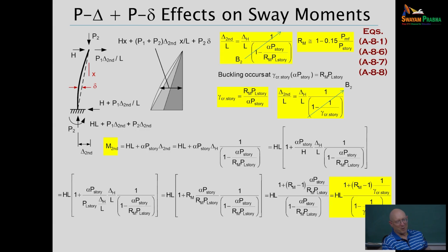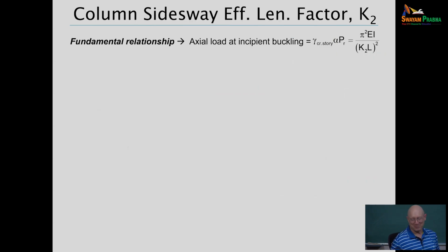Yeah, the formula for R sub m is kind of a gross curve fit. 0.85 may not really be 0.85. It's typically conservative. There's always a dangerous thing: anytime you say that's conservative, somebody says, well, here's a case where it's not. I can show you a case where it's not conservative, but it typically is. We'll look at some very interesting, surprising things here sometimes in what we're going to be discussing.